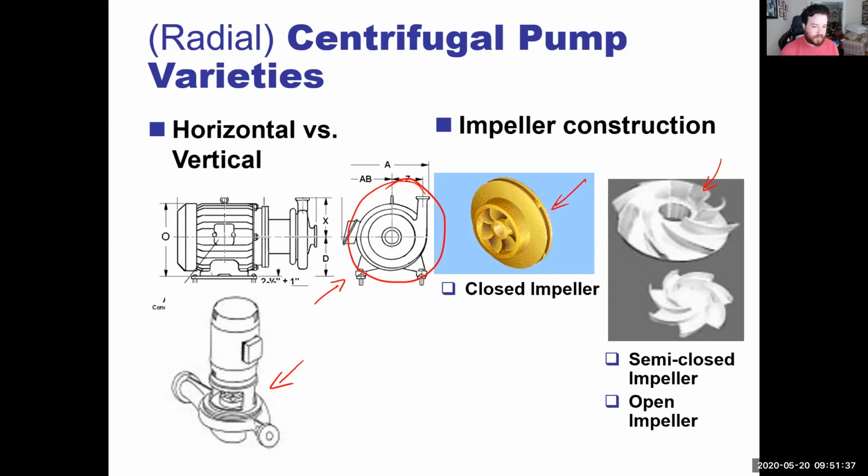You're going to know that you need to put in a new seal on the shaft over here, because that's where it's leaking from, or there's the gasket in between these two portions here. You don't want to take a pump offline that's working, it's just leaking, and make it so that it's not able to work because you took it apart and you don't have the right parts.